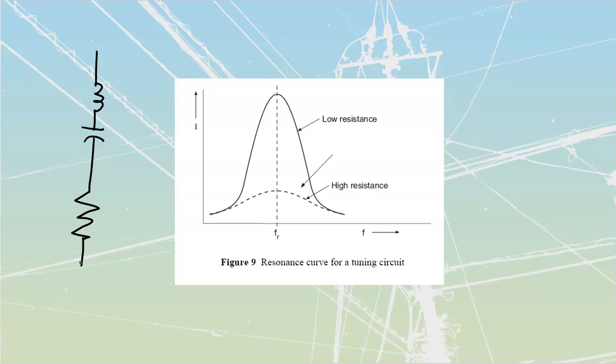In simplified form, if I have an antenna type of circuit, and that's where we would be picking these things up from, I would have a low value of resistance, R low, and then as I vary this capacitance over here, I'd be taking it across, and then all of a sudden hit this point where I'm at my resonant frequency.